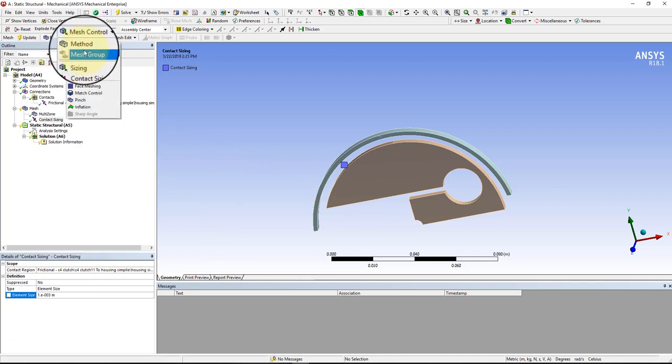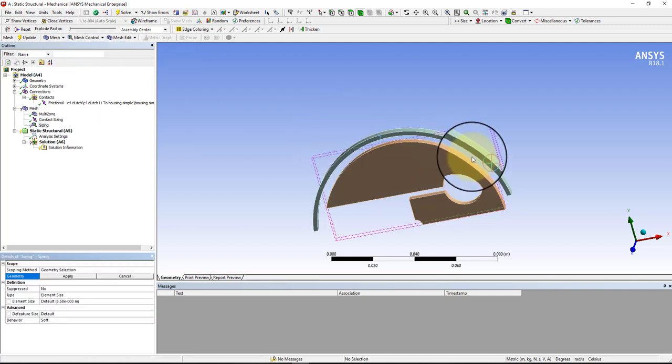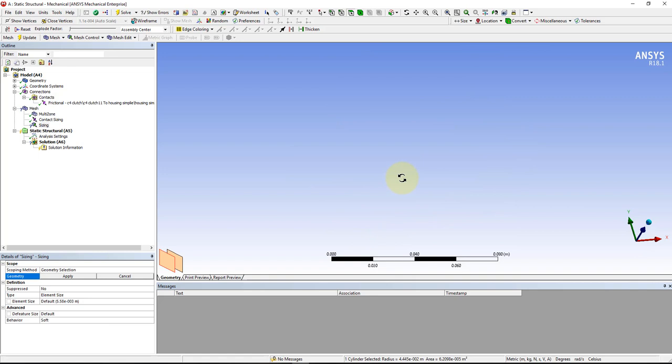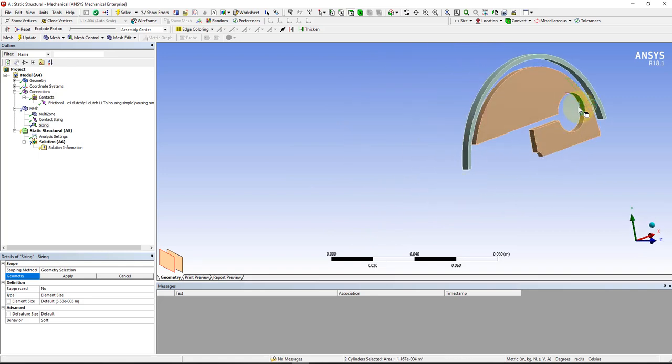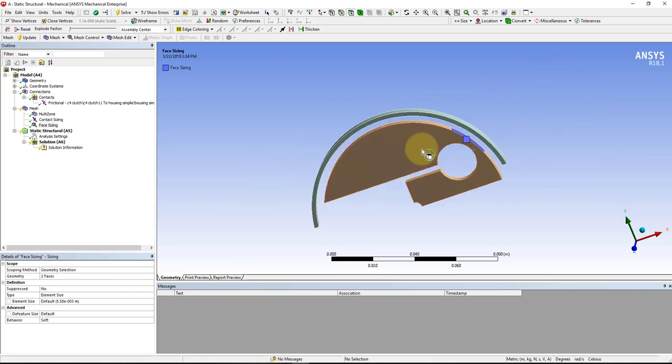We also, let's just go ahead and set a sizing constraint, and let's select the face. So these faces right here are important because that's the area that's actually bending. And in this region, where mostly it's a mass creating a force, it doesn't take a lot of refinement in there, but in this region it's a stiffness question, so we want to make sure we have a fine enough mesh to handle that. We'll just go ahead and create 1 millimeter elements there and see what that looks like. Let's go ahead and create our mesh.